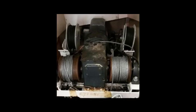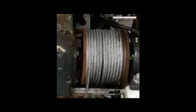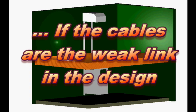Standards for factors of safety are all over the place these days and also important in elevator design. Most famously, the standard factor of safety for any cables used in elevators is 11. So if space allowed, you could pack 11 times the weight into what an elevator's load capacity placard says and probably survive the ride if the cables were the weak link in the system.